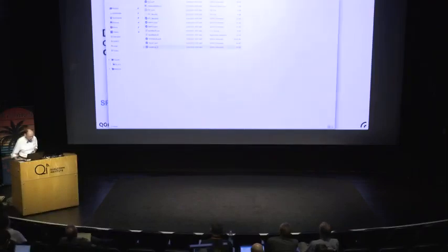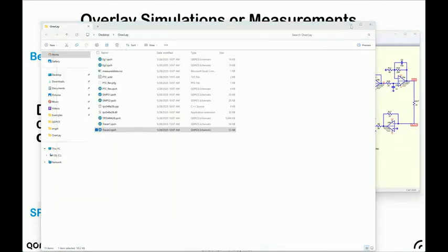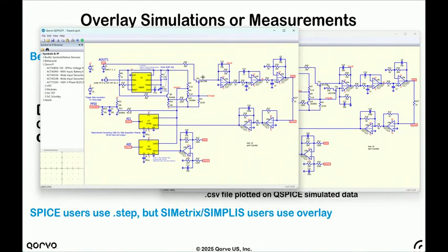Let's take, okay, great. Here is, I mentioned I fell in love with KiCad because I had to do a curve tracer, and this is part of the curve tracer circuit. The curve tracer didn't use a PCI data converter. It used USB because I didn't want to bring my desktop computer into my lab. I just used a notebook computer. So I was basically digitizing DC levels for a pulse tester. So I put DC levels on the thing. I would pulse the waveform, and then I use sample and holds to store it. And the square pulse was shaped to a Gaussian so that I could use an electrometer type circuit, and the electrometer could keep the virtual ground near ground and not pop a gate while it was working. So that's the way the thing worked.